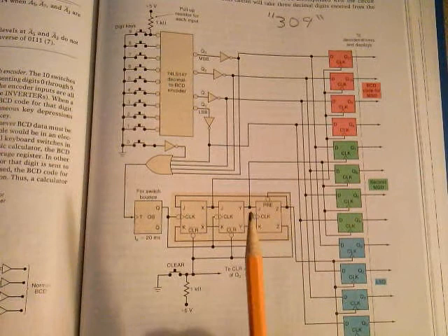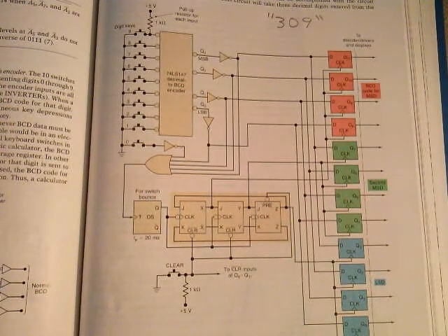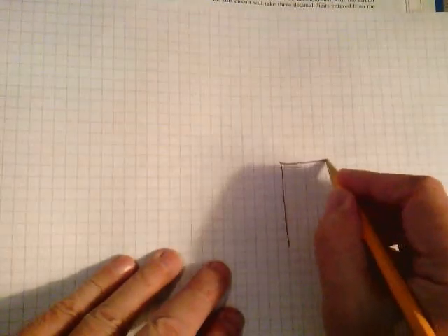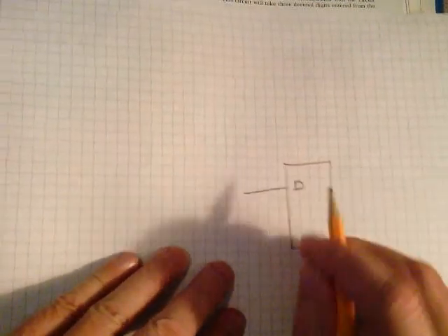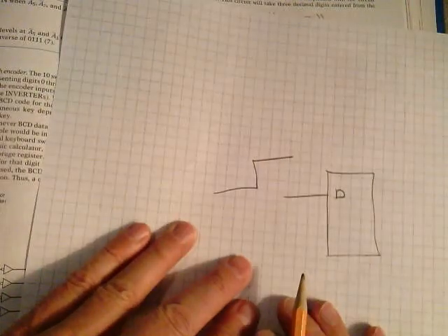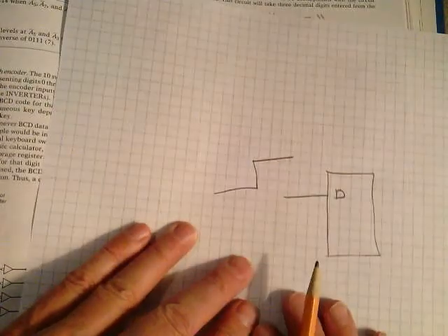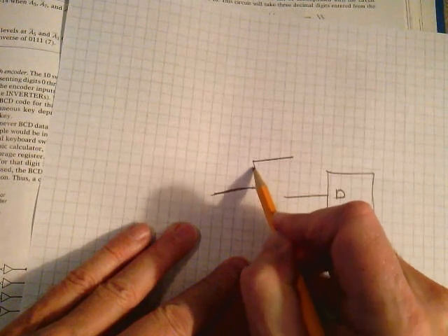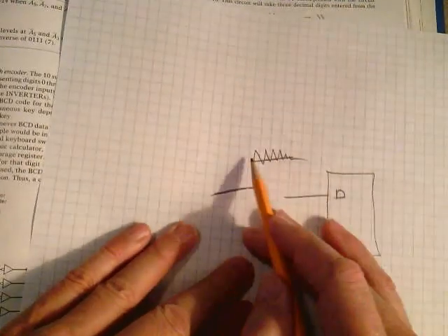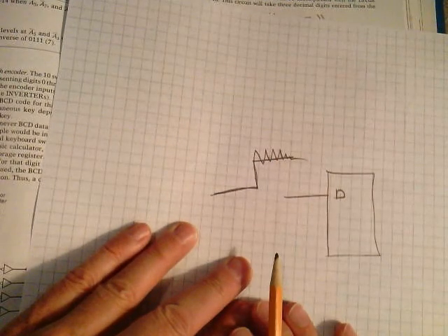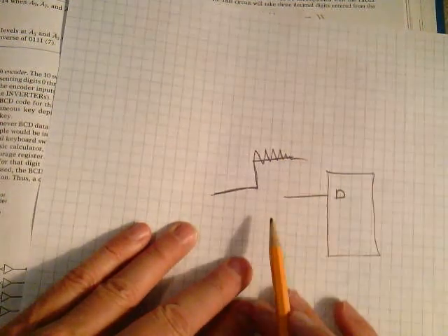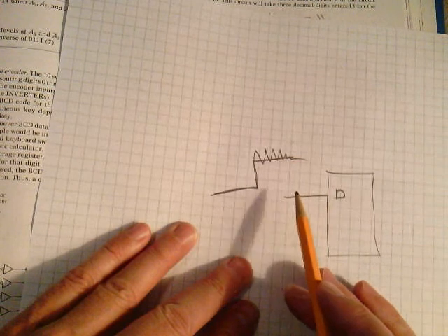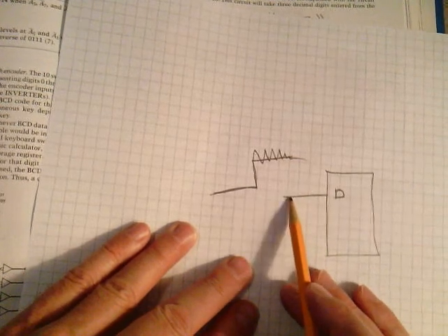Let me show you what I mean by that, because that's important. Whenever you set up an input to a flip-flop, here's a D flip-flop, we're going to set up that input, and you go to a 1, or you go to a 0. It doesn't look like that. There's a transient. It goes like this. It rings because of the inductance and capacitance in all the wires. That's why you have to allow for setup and hold times on these flip-flops we talked about.